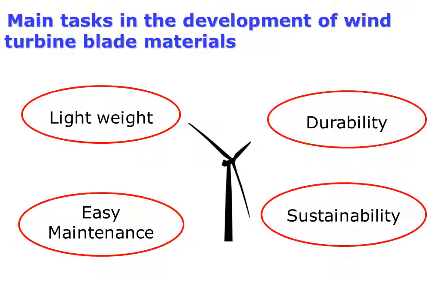Such large expansion of wind energy sets several important challenges from materials science viewpoint. First, the durability and lifetime of wind turbines should be extended. Wind turbines are large and expensive structures, and it is just too expensive to replace them every 25 years. Low weight of blade composites is in fact related to the lifetime extension. Lower weight means lower load on blades, and thus longer lifetime.